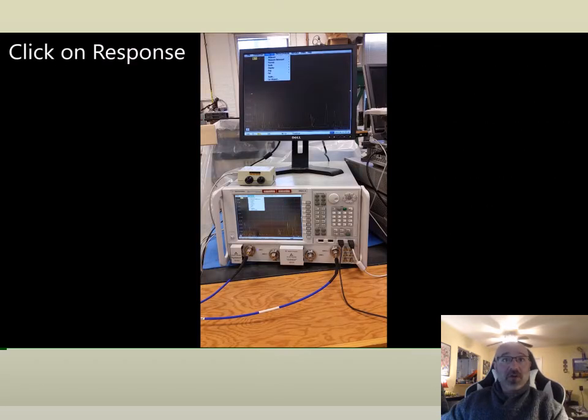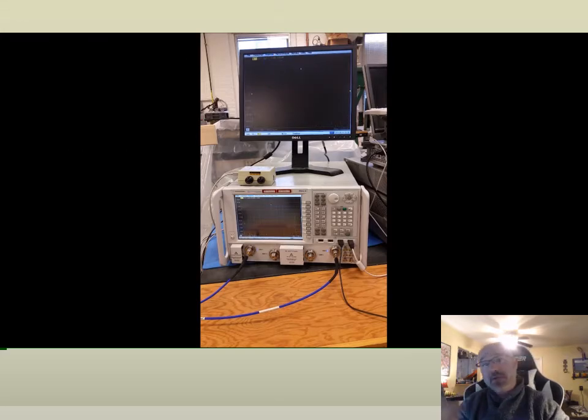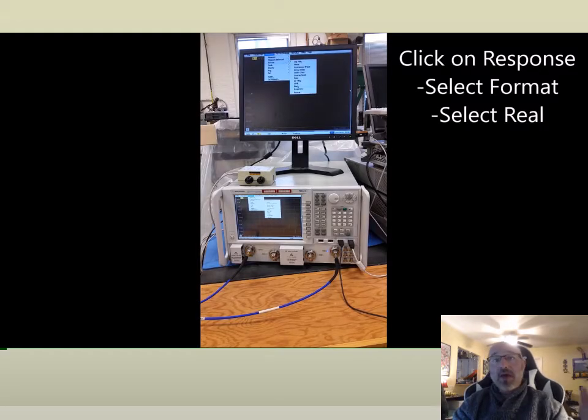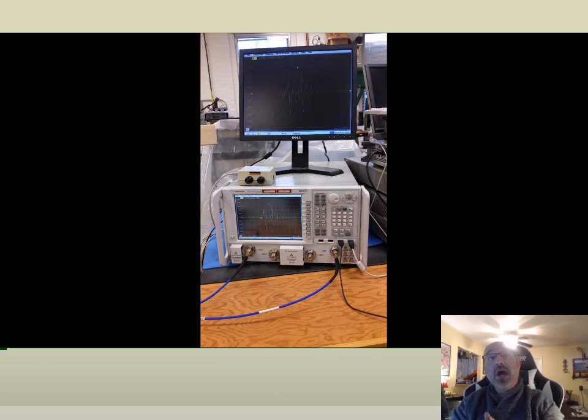So all of our signal for what we're sending through our antennas is programmed through this network analyzer here. This lets us know we're sending out on port 1, we're receiving on port 2, this is the signal we're sending, this is the size of our signal, the amplitude, the frequency of our signal, and all of that is just the information for what's being sent in and out of our send and receive signals that are then being moved on this linear drive.